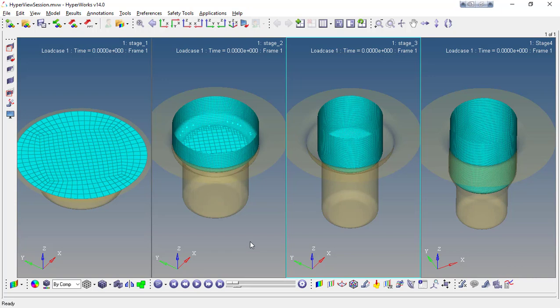Such multi-stage analyses are quite difficult, critical not in terms of CAE, but because such analysis needs very accurate and precise geometries and tool design. If there is any small error or small change in tool design, the complete simulation result will change. Even a small clearance between tooling, punch and die and punch and binder, may completely change your simulation result as well as the manufactured component.